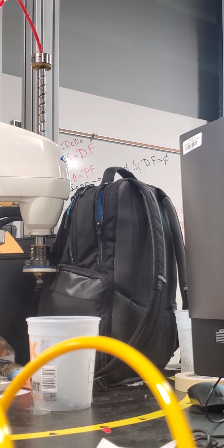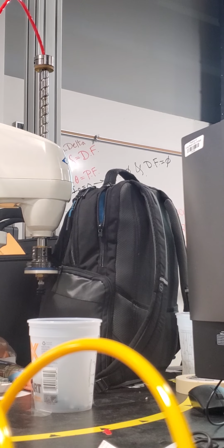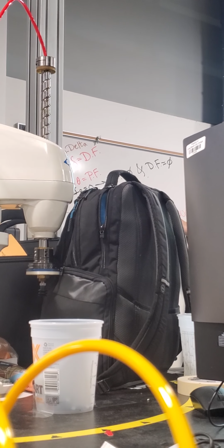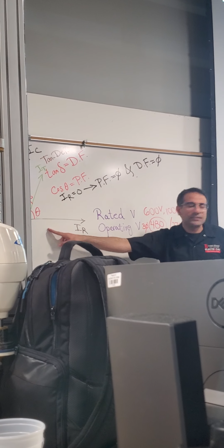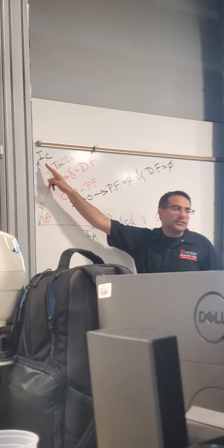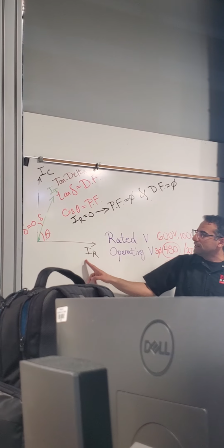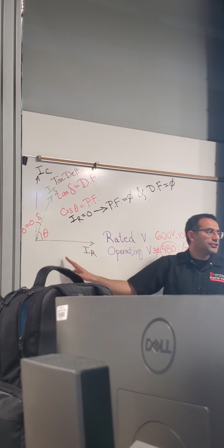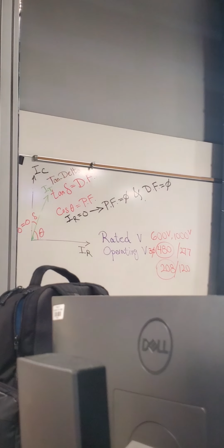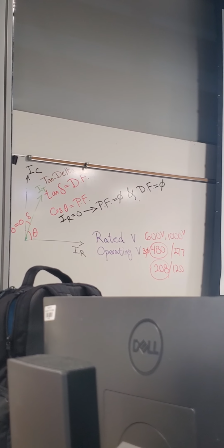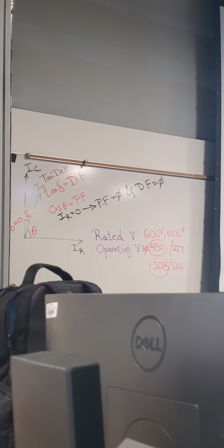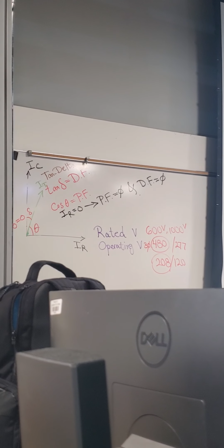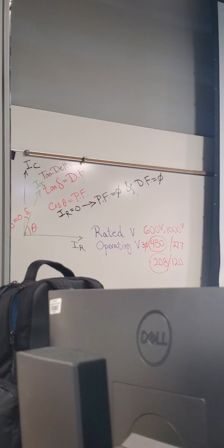So if you hear a tan delta test, the concept is similar to power factor. The brain of the system is measuring the same thing. It's measuring the charging current and the leakage current of the insulation. Then it does the internal calculation, and at the end it's going to give you the dissipation factor or power factor. That's going to be the output of the test instrument.